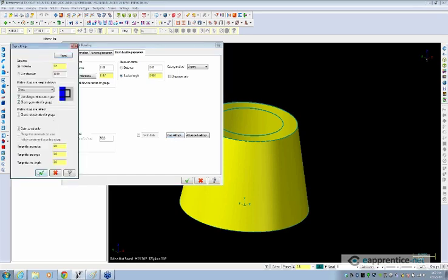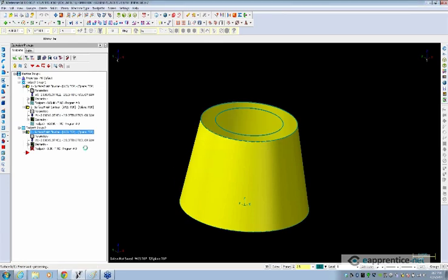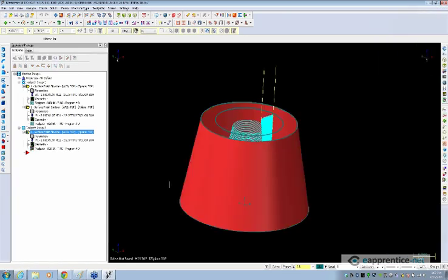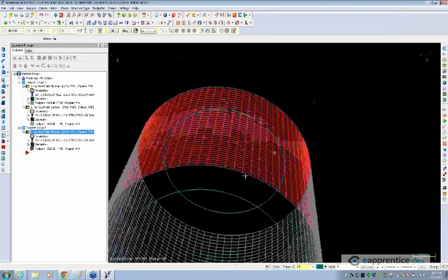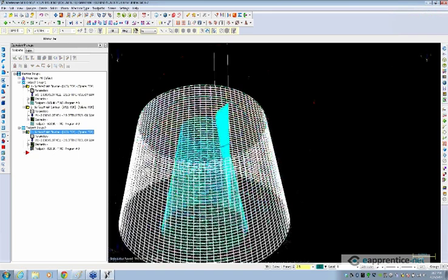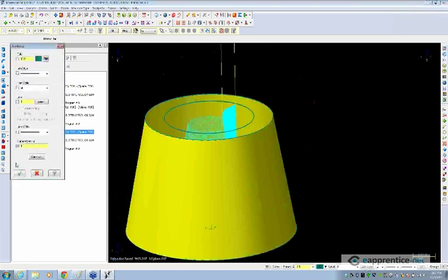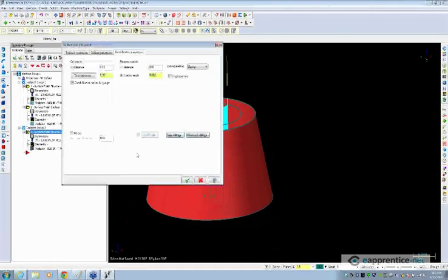Make sure all these are, again, set to the default settings. When I do just the default settings, it actually won't allow the toolpath to undercut. So we'll let it process this flowline toolpath, and you can see that we're getting some kind of strange gap motion there, and it's going to crash into our surface and give us a bad result. Let me just change that surface density again. That's better. Okay. So when we set this up for undercutting, we need to adjust the gap settings.